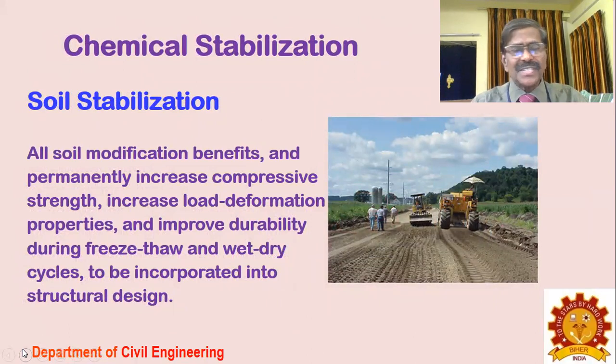Soil stabilization is done. All soil modification benefits, and it permanently increases the compressive strength, increases load deformation properties, and improves the durability during freeze-thaw and wet-dry cycles, to be incorporated into the structural designs. That means you have to improve the soil as a structural material. It forms a part of the structural composition in your structure.